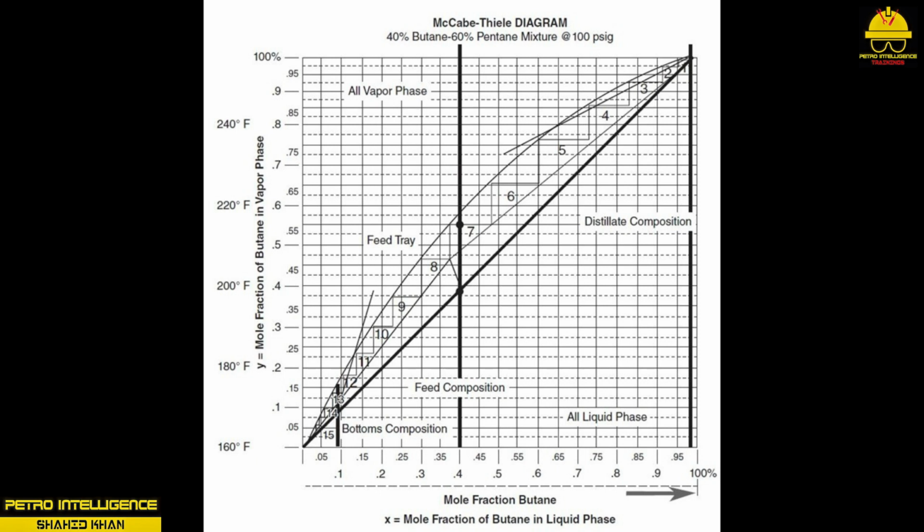The initial boiling point is often described as the temperature where the mixture first starts to boil or evolve vapors. As the mixture continues to boil, vaporization occurs, and the lighter components begin to boil off. As this process continues, the composition of the remaining mixture will become heavier. In order to boil this material, the temperature will need to be adjusted upward. The final boiling point occurs when the heaviest component boils and this temperature is recorded.